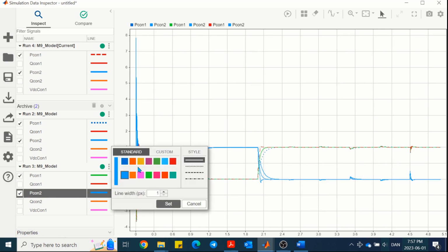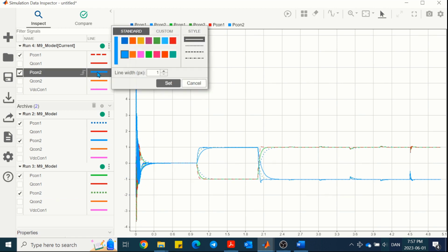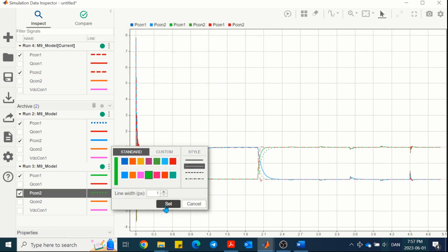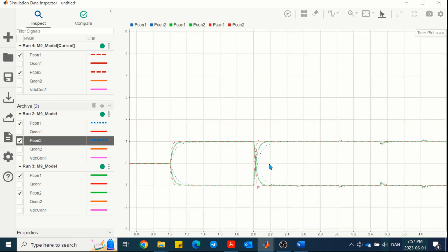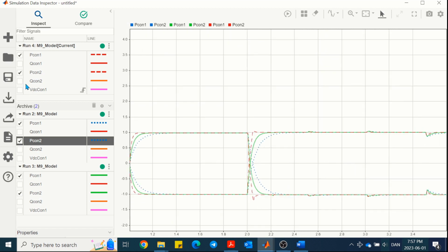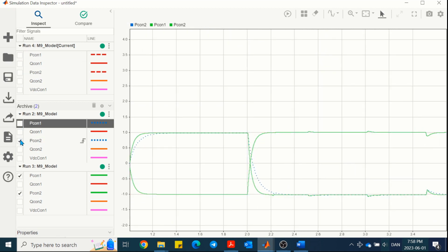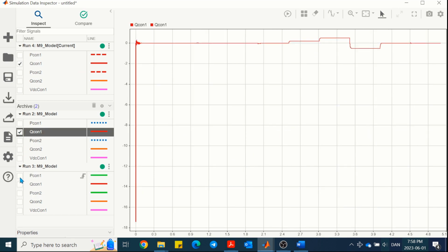We can observe the response of converter 2. That should be similar because converter 2 is in VDC control mode, and it is simply balancing the power in the DC link. So whatever power is injected, the other converter is extracting or injecting if necessary to balance the power. So they will show a similar response. Also, it's nice to observe that this 2 times faster or slower really makes it look like 2 times faster on the control response also.